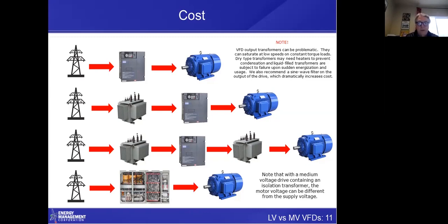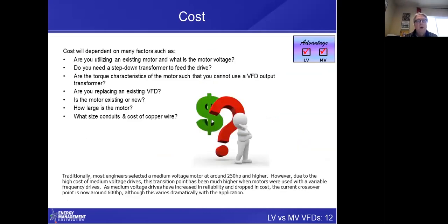You'll notice that that drive has an isolation transformer built into the drive. We highly recommend that you have that. I wouldn't want to purchase a drive that didn't have an isolation transformer built in. And if you do that, then your input voltage and your output voltage can be different. And that's something that is not the case with low voltage. So cost will depend upon all of those factors.